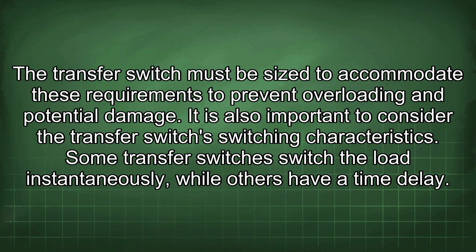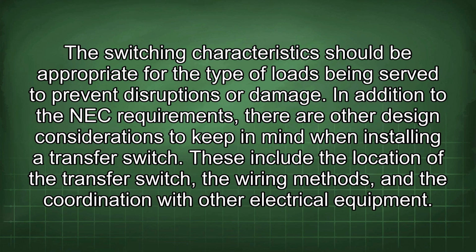It is also important to consider the transfer switch's switching characteristics. Some transfer switches switch the load instantaneously, while others have a time delay. The switching characteristics should be appropriate for the type of loads being served to prevent disruptions or damage.